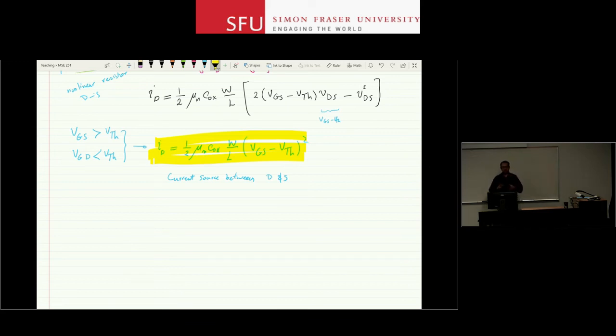You can make the device larger or smaller if you're making an IC, but there's really not much that you can do beyond that. And in here for a MOSFET, that tool is the change in W and L ratio. If you make the device wider, it's like you put multiple of these in parallel, and therefore you get W times the current out of this thing.